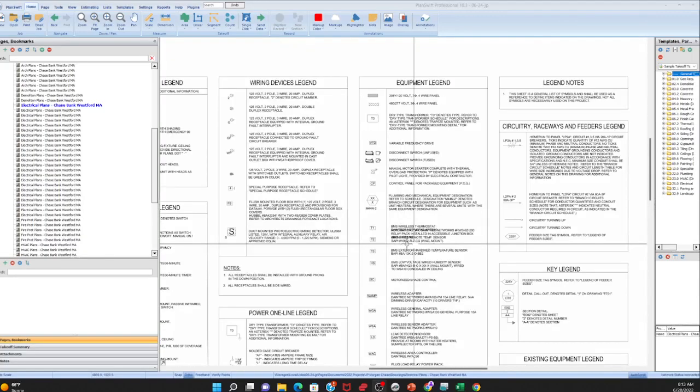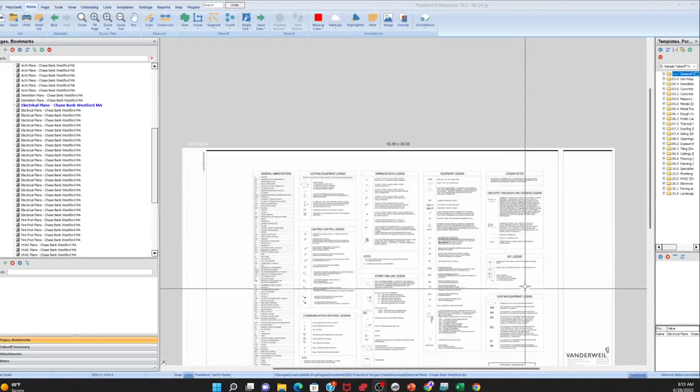These sets of plans we're going through are for the high voltage electrician, which is the electrician that provides the power to the building, power to the lights, all of that. Then the low voltage electrician does the wiring for the HVAC, the telephone and the computers. So that's the difference: the high voltage electrician provides all the conduit and junction boxes those other low voltage electricians need.